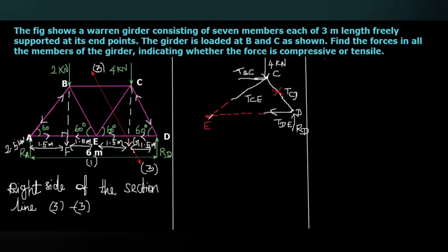When I take moment about E, here actually 5 forces are there: TBC, TCE, TDE, the point load RD and 4 kilonewton.